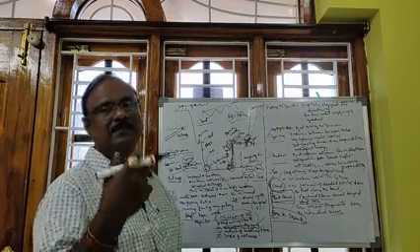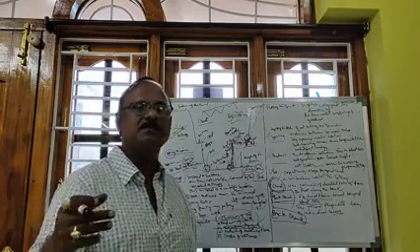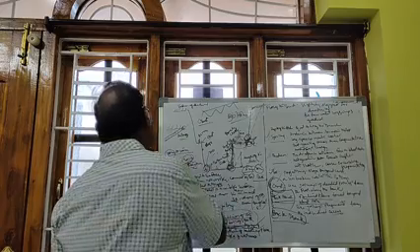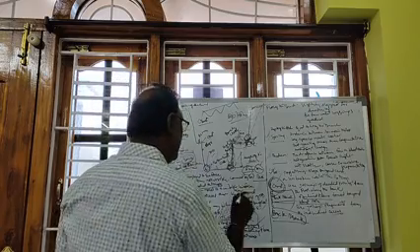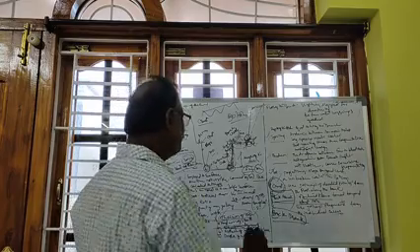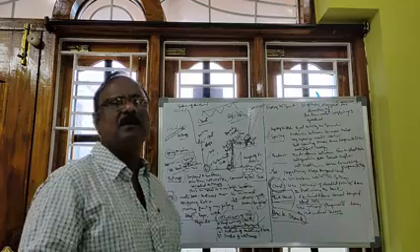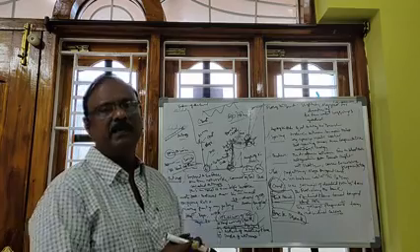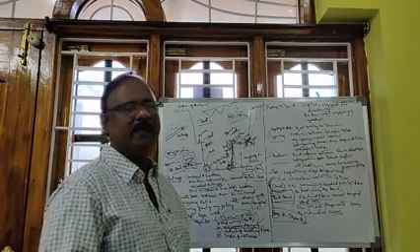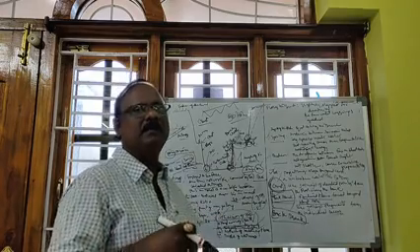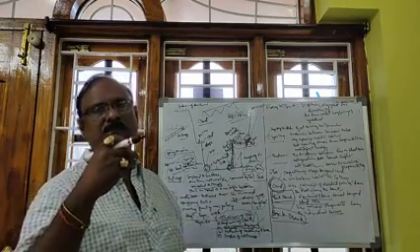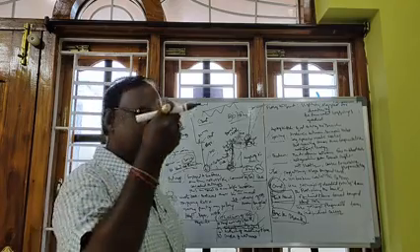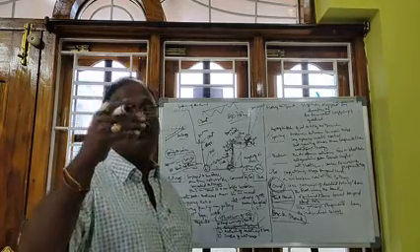The height of the benches is 30 meters. For 300 meters removal of the overburden, 10 vertical benches are required. So this depends on the thickness of the OB and the hardness of the strata. When the strata are very hard, such as igneous rocks, with quartz, corundum, and apatite available in the rock face, the height of the bench can be much more than 10 meters.